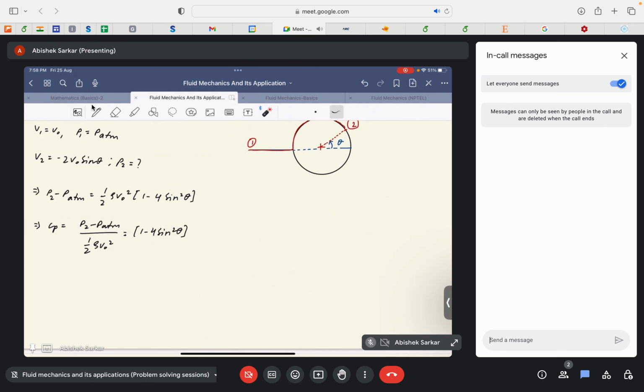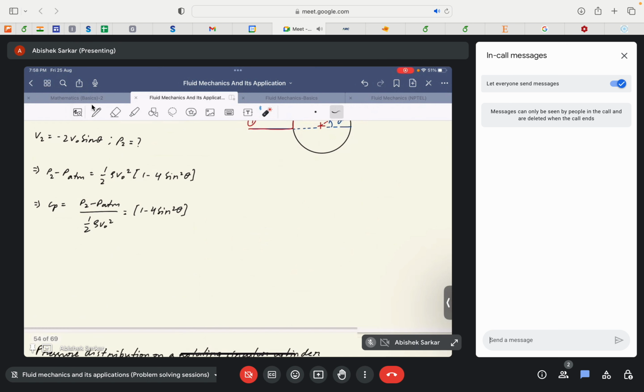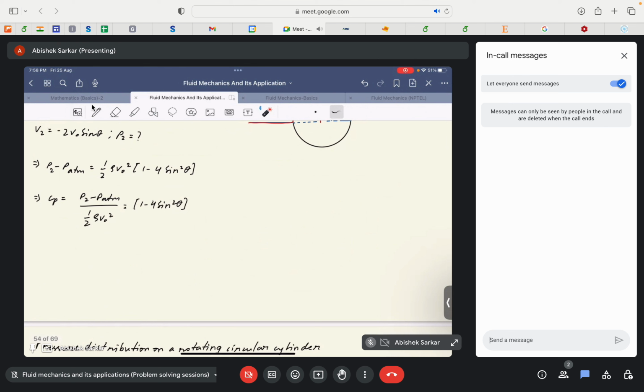When we discuss it, we will see how these flow fields are obtained using stream functions and the potential function, and how stream functions are generated by considering the sum of, say, a source and a sink.